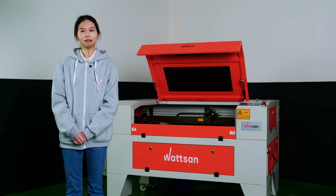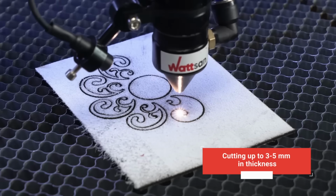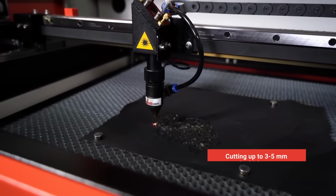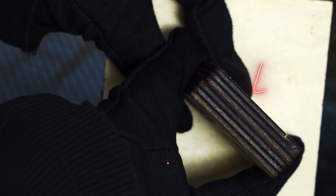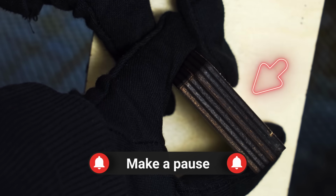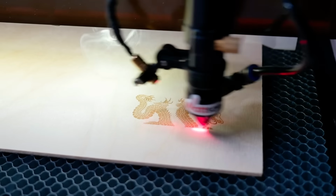Though cutting is available only for thin materials up to 3 to 5 millimeters in thickness, with enough power and good air blow, you may cut thicker workpieces. However, the edge is going to be burnt and sloped. That's why short focus lenses are considered to be the right ones for engraving.